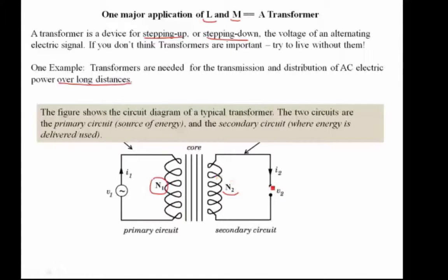If you had a load across these two points right here, you would have a current that is generated because of the closed circuit. If you have no resistor or load across here, then there's no current. There will, however, be a voltage. So there's an open circuit EMF that's generated across these two wires. To look at a usual transformer, you have these windings sharing a core of magnetic material. And we'll talk a little bit about that.